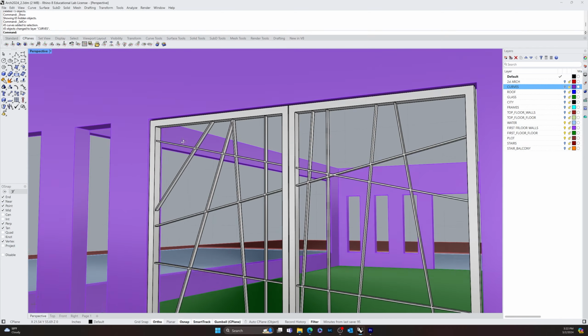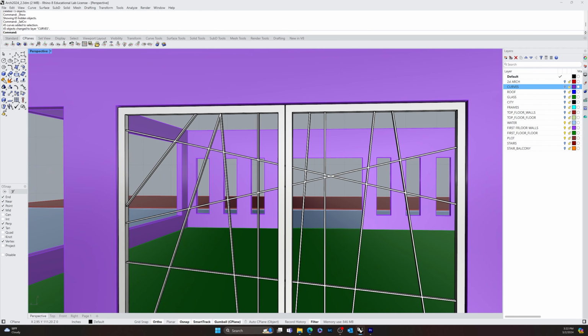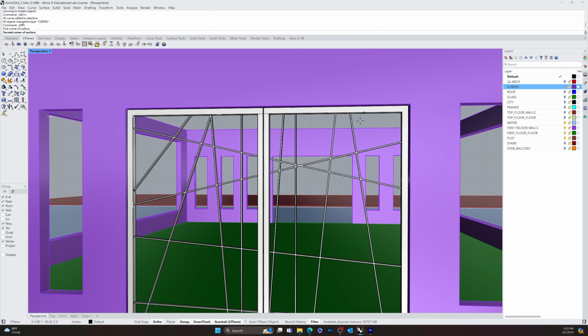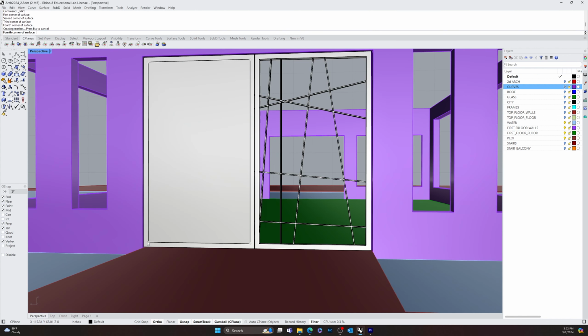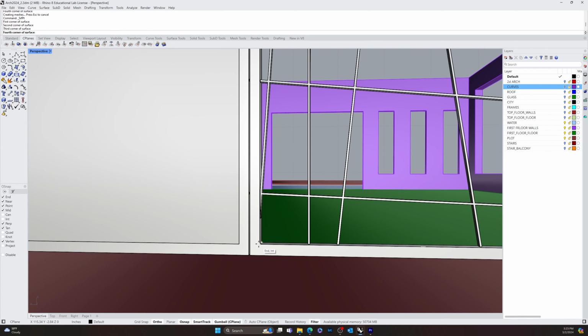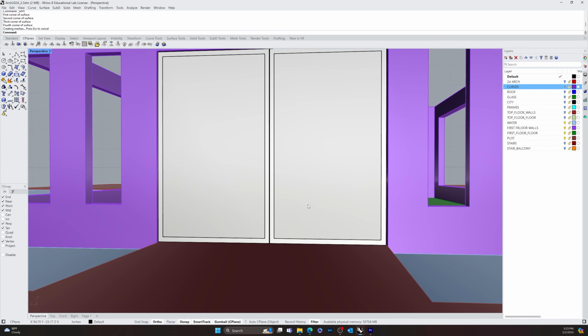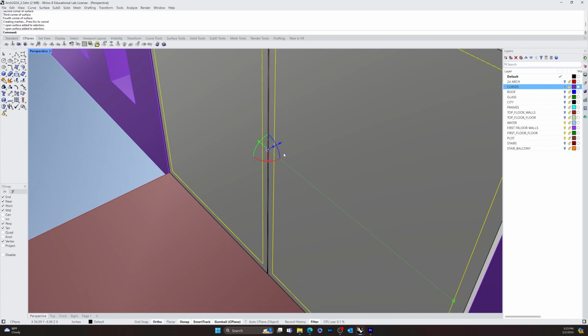And then all you got to do is create a glass panel on the inside of this, and that's easily done just by drawing a surface from the inside of this. And enter brings up the same command back over here. And then we push these two back.